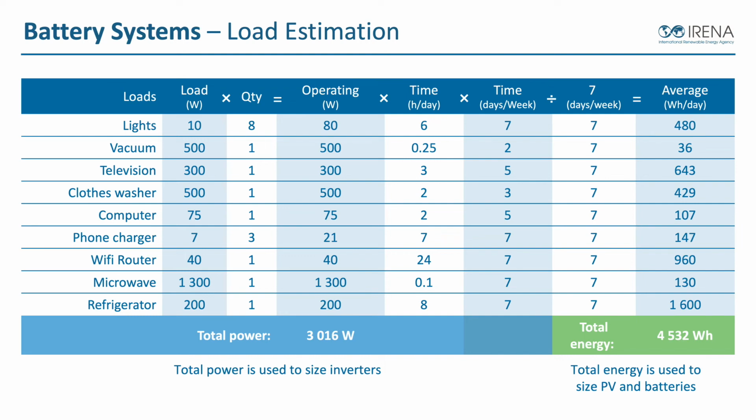If we estimate too low, we're going to have a system that's undersized, which means the battery's too small, the solar's too small, and it's going to not meet our needs, which means either we're going to run out of power, or if we have a backup system, the generator is going to run a lot longer than we had expected. So we want to do our best to estimate our loads and to try to get averages. We know things change in the way we use devices in our homes or businesses, but we want to try to do the best we can.